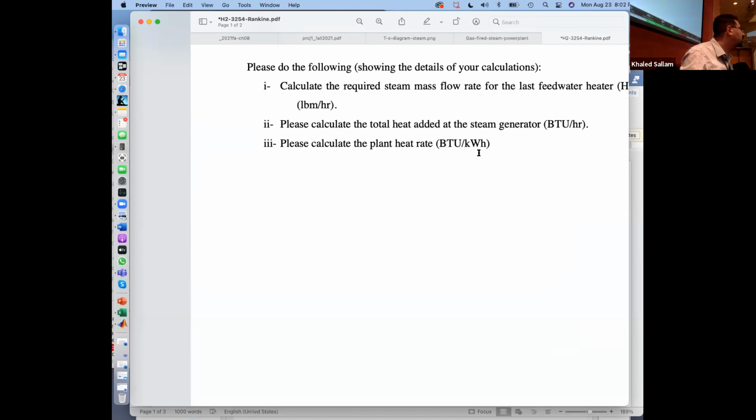Why do they do this? Because they sell the kilowatt hour to us at 11 cents, and they buy the BTU from the natural gas company. And so they want to see this number. When this number is 9,000, they are happy. Or like 8,000, it's happy. When this number goes to 10,000, that means their efficiency goes down. So they panic. Like, oh my God, we are not making money here, because they are paying a lot for little they are making.